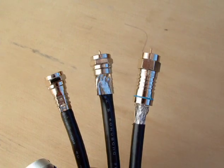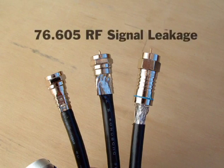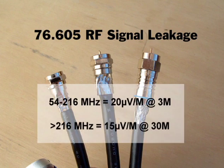Improper coax and F connector installation is also the leading cause of signal egress from the home. Now, the FCC establishes strict signal egress limits on the cable industry to prevent cable signal interference to other services, especially aircraft navigation. Now, if your installation has found a leak, the cable operator will disconnect service and not reconnect it until you can show that the source of leakage has been found and corrected. So make sure you get it right the first time.